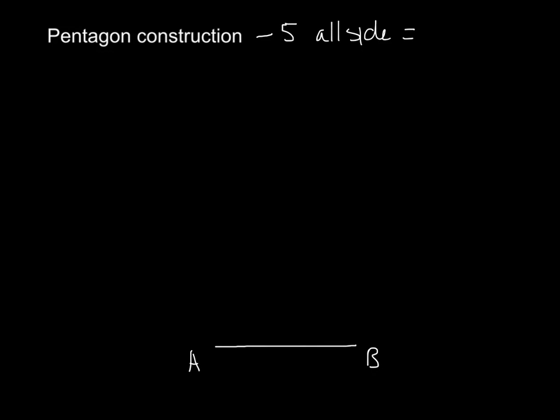So using line AB, the first thing we do is we bisect line AB, which means we divide it perfectly in half, and we divide it at 90 degrees. We'll start by putting our compass at A, going more than half, and remember, I'm just guessing. Let's just say it's about there, and we're going to arc down over here, and we're going to find a point somewhere down here. We'll switch the compass around, put it now at B, and arc down over here. Remember, we'll be arcing up here as well, and up from our A, arcing up there as well, so that we can bisect AB perfectly in line, which creates line CD.